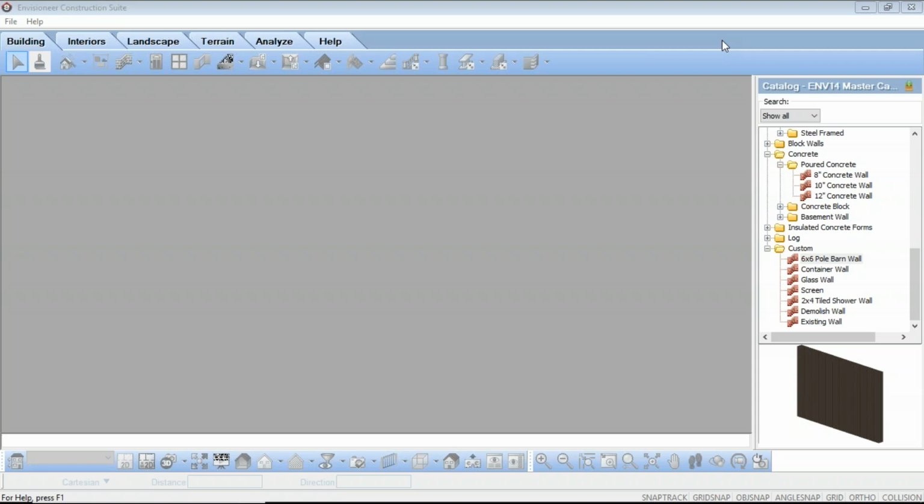Like I mentioned, today's class is on creating a template. By default, every new project you start is based on a template. A template determines what settings new projects will have, such as the unit of measure and building location settings. You can even include your building elements in a template, or a complete set of working drawing sheets with custom title blocks. You can create a template out of any drawing by simply saving it into your templates directory. To use the template in any new drawings, all you need to do is select it from the templates in your startup options.